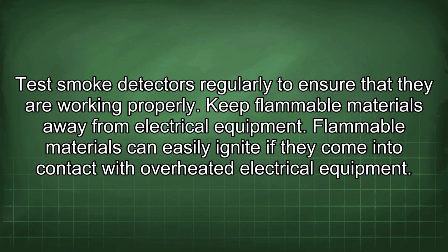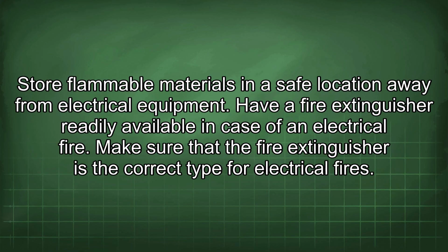Keep flammable materials away from electrical equipment. Flammable materials can easily ignite if they come into contact with overheated electrical equipment. Store flammable materials in a safe location away from electrical equipment.